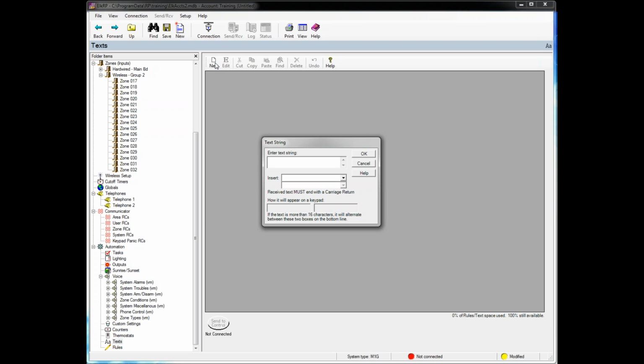So even though it's something that we don't already integrate with, as long as we have some RS-232 ASCII strings, maybe something like a pool pump or a pool automation control, a Jandy system or something. I think they published the RS-232 protocol, so you could create those custom strings to turn on and off the pump or the filter or the lights and so forth. Wouldn't be able to get temperature readings because that would probably take way too many strings, but for some general purpose automation, certainly doable using this feature.